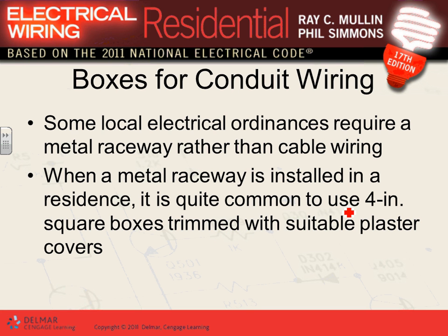Local electrical codes require metal raceways. Sometimes, like in Chicago, they require you to use metallic wireways instead of MC cable. Remember, how many wiring methods we have? 50 plus. So you can wire an outlet with an MC cable, AC cable, any other cable. In certain places, an MC cable is not an approved wire method.